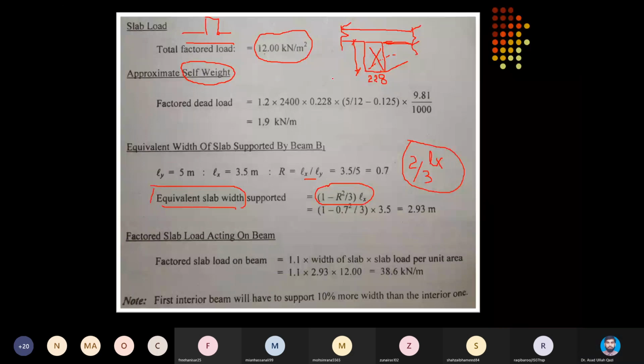So a very conservative selection of the beam gross depth will be one which will envelop almost all the serviceability required depths, to get the deflections within limits and to keep the crack widths minimum. If you consult the table given in chapter 9, you will get, based on various end conditions and steel grades, the recommended depth of the beams.